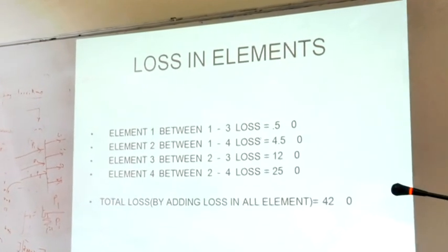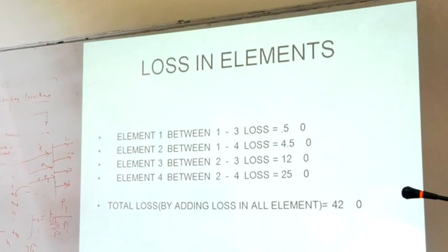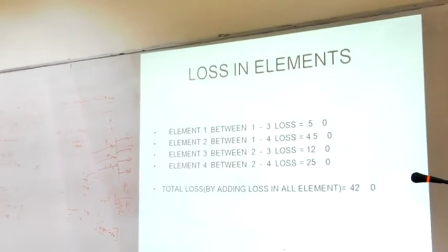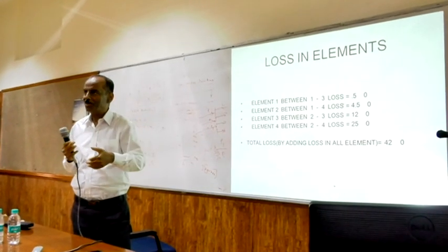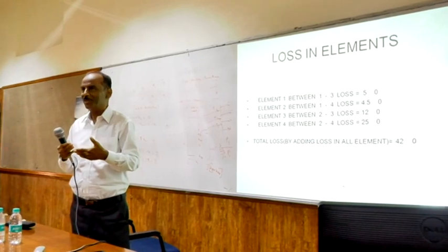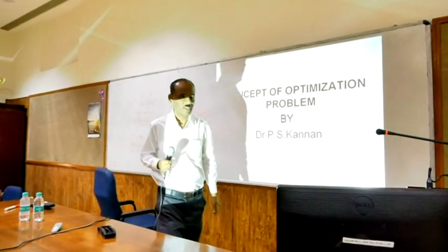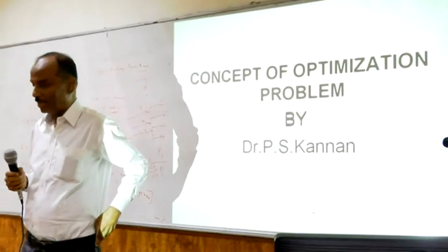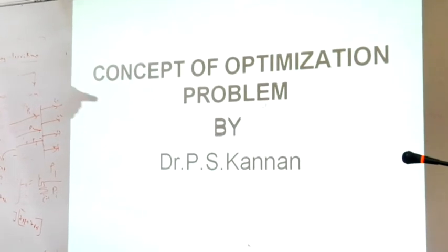How can you verify? You know how much the sources contribute for each load. You subtract it, and the remaining you add, and you can get the total loss. And I squared R loss you can add, and you can verify exactly. It is called power balance. Any doubt about these things? And next, I have to complete this, and then finally I come to the practical demonstration.